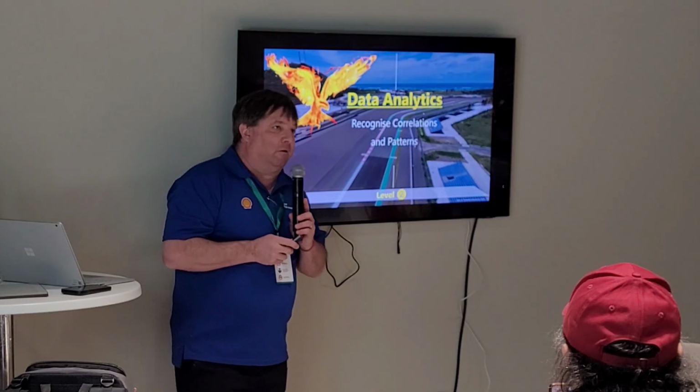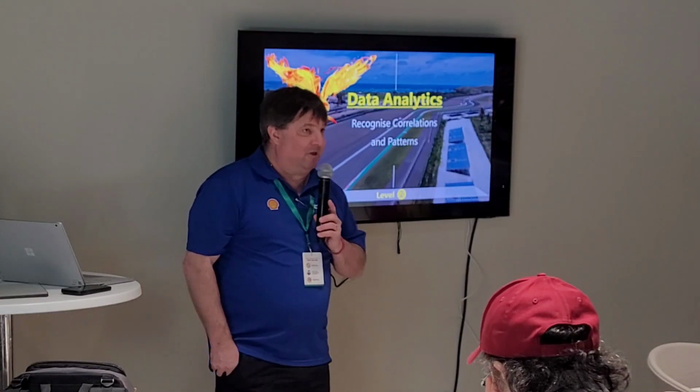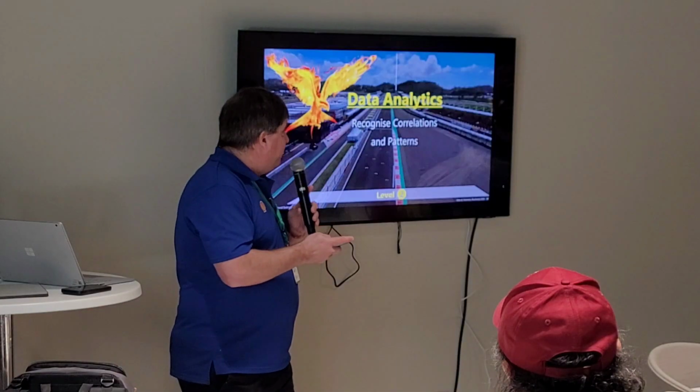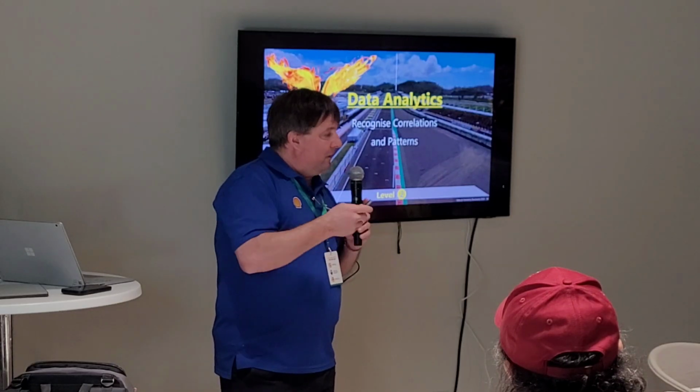So are there any questions on this first level so far? Creating a telemetry system is not an easy task. There is also a lot of noise in the engine compartment, I tell you. EMI is a problem, via vibration, heat. So you have to be careful that you protect your electronics and make sure it's kind of in a Faraday cage. Yeah. In the upcoming webcasts or bootcamps, maybe we go deeper into this technology, because I want to know actually what can you build yourself and where do you need know-how from us.